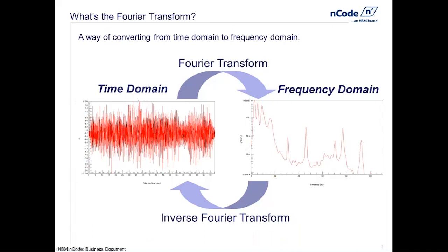Speaking of vibration, if you speak with someone in an NVH lab, or maybe your employer has a vibes group, they like to talk a lot about the time domain and the frequency domain. Now typically, measured loading data, how someone actually uses the part we're building or designing, is measured in the time domain, and that's the squiggly line over on the left side here. This is G loading or moments, forces, whatever it is, something versus time.